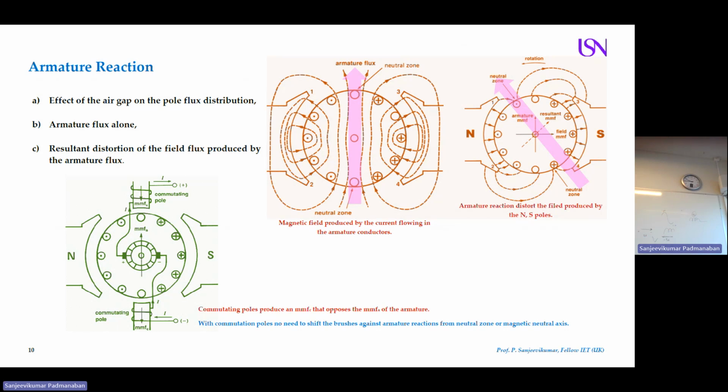Third possibility: the compensating winding may not be connected, because the manufacturer is confident in their experience that a compensating winding is not required. My machine is running well, but depending on the environmental conditions and continuous use of the machine, the problem can happen at any time. Then you have to open the machine and connect the compensating winding inside. Clearly? Any doubt?